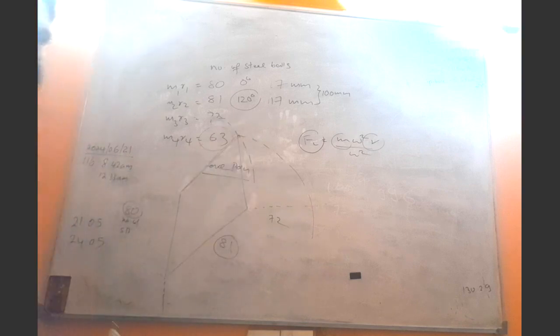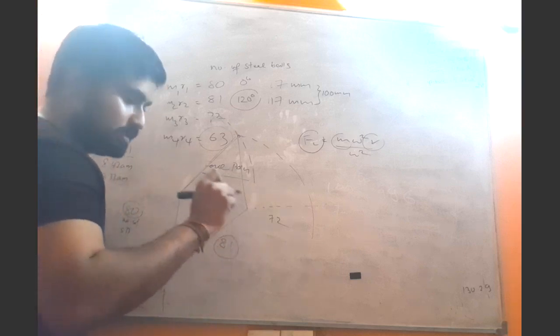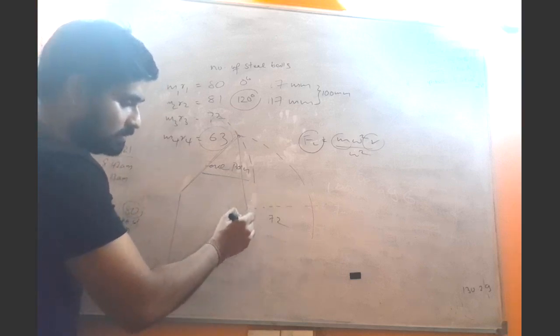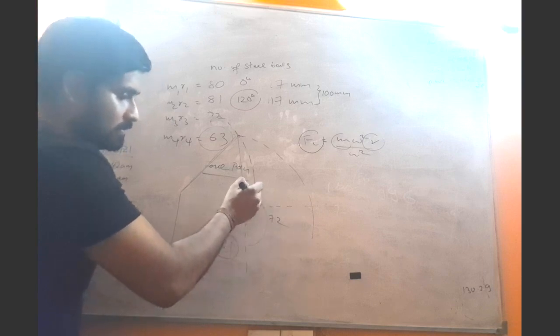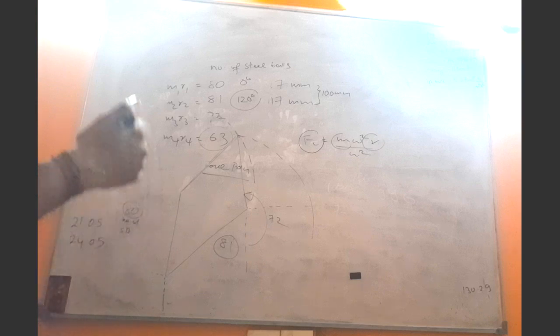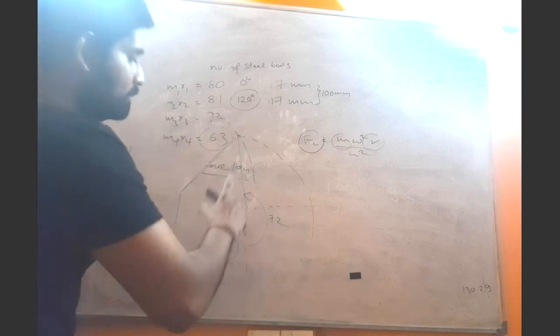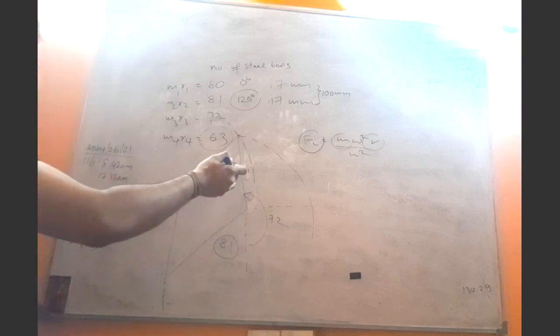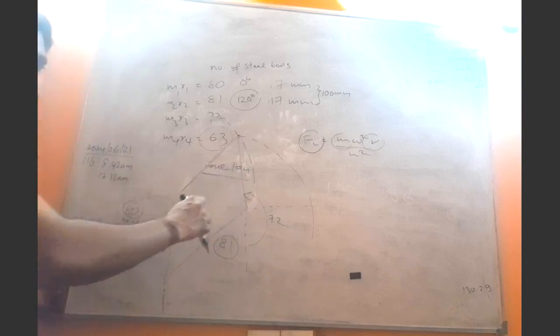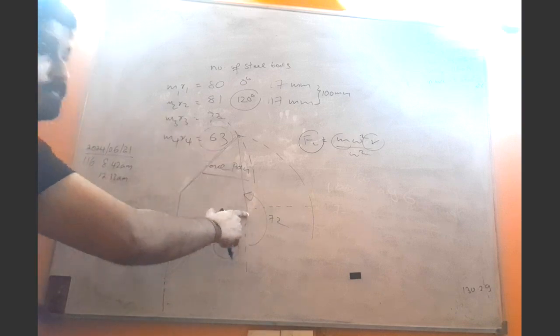Now how to find the angular position of the third mass? Angles are always measured with respect to the downward vertical. Measure this angle. If you want to measure that angle for the third mass, go to the last point where you ended the previous vector.